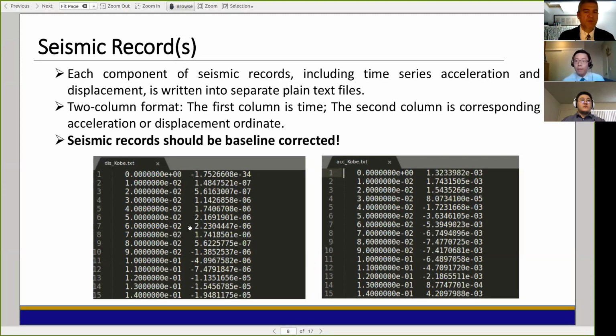A note: these are surface records that are going to be deconvolved, and then propagated back using DRM, using Real-ESSI. DRM, the domain reduction method, is a very physics-based method. It's very sensitive to wrong motions, to wrong waves. So you can't just put in any wave.